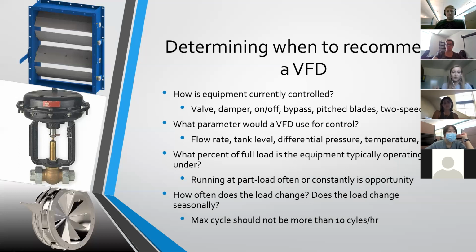And whatever control method you have, that's probably going to be using more energy than if you slowed that speed down to control down to that flow rate. So yeah, running at part load often or even constantly is a huge opportunity for a VFD.